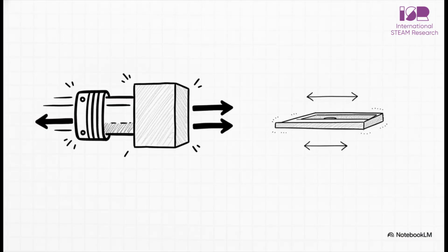If we break down the physical anatomy of how this straight-line motion actually happens, you basically have a piston housed inside a cylindrical barrel. Energy gets introduced through either the cap end or the rod end ports. That energy forces the internal piston, along with the attached piston rod, to extend or retract in a perfectly straight line, and it's all safely guided and secured by the tie rod. A classic, everyday example of this linear design is the piston used in traditional car engines and pumps. But what exactly is in there pushing that piston?